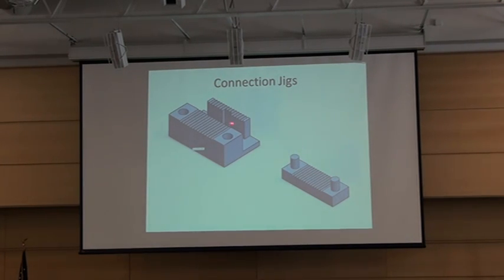So this is our wiring jig, and basically it's got a bunch of little grooves that you can lay the wires in, and it's got a top piece that kind of flips down and connects. You can see where the holes in the bosses are, and there's a spot here for the connector. The connector sits in there. Put the wires in, put this down to hold the wires in place while you get them all lined up in the correct order, and then you can just put the other half of the connector in, and you're good to go. You have one terminated cable.